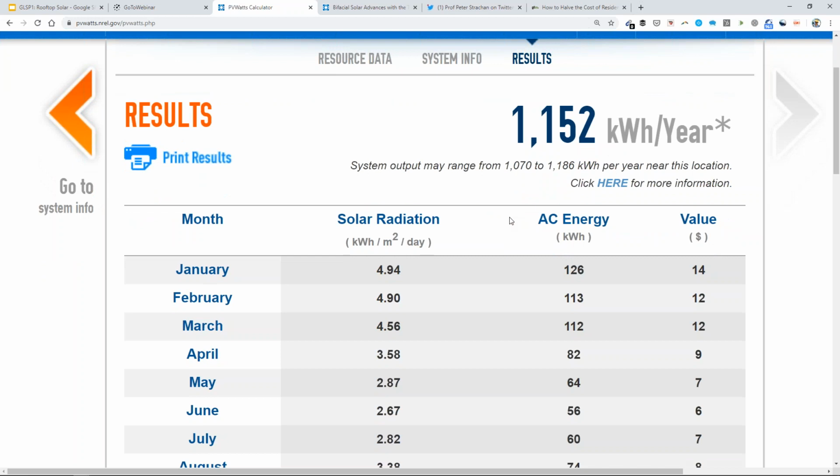And so, I'm always fascinated with the obsession of having solar face in an ideal manner, because it's not like the solar designer is going to adjust the tilt of the roof. If you do, you're going to make a mistake, because as an installer, I would much rather have the roof be walkable and then maybe extend some panels down the side of the building than have a 65-degree tilt angle project. The site access and walkability of the site is what makes a project cost cheap. So rather than orient the building to the solar array, just admit that the tilt angle and orientation really do not matter as much as having big open spaces to work with.